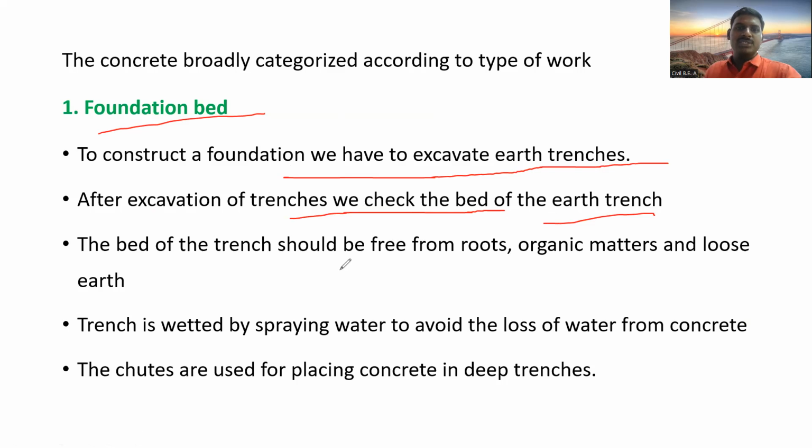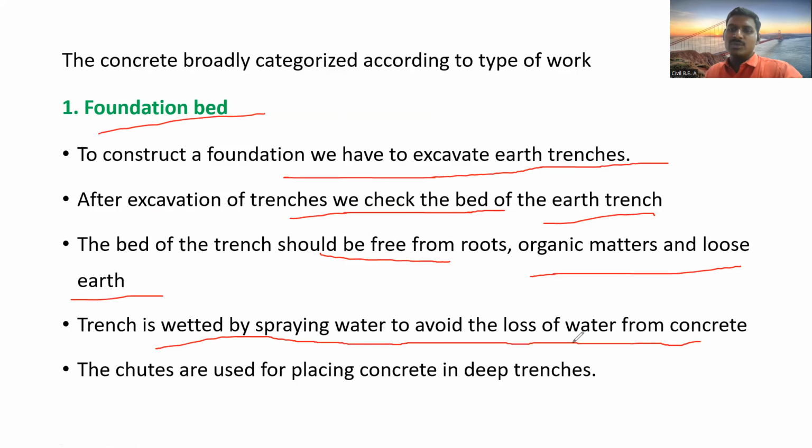The bed of the trench should be free from roots and organic matter, and we have to remove loose earth. Then the trench is wetted by spraying water to avoid loss of water from the concrete, and tubes are used for placing concrete in deep trenches. This is the work we have to do to place the concrete in the foundation bed.